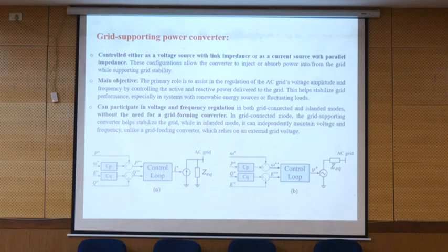And then they said, for example, now I inject 10 kilowatt, but the frequency drops. When the frequency drops, it means that we need to increase the active power to return back frequency to this borderline. So by this, you increase the value of the active power, then compensate the frequency of the system.